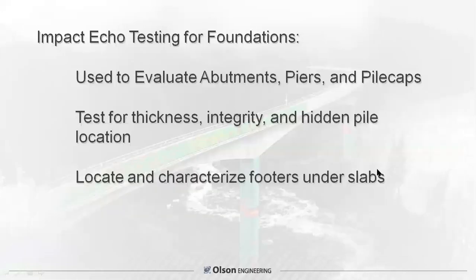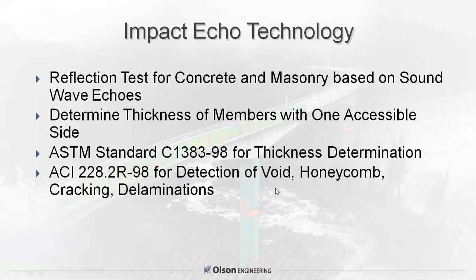So we use this to evaluate abutments, piers, pile caps. How thick is your pile cap? We've used it to locate piles underneath pile caps because you can locate areas where there is not an echo from the bottom of your pile cap. We've used it to test for thickness and integrity in hidden pile locations and looking for footers.